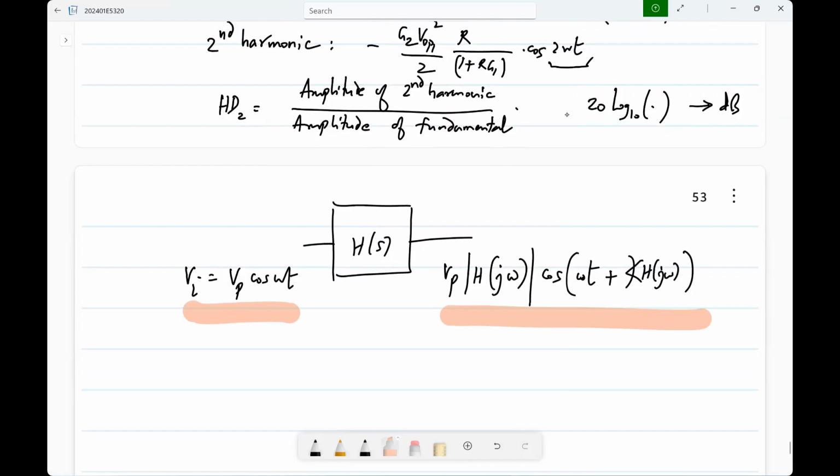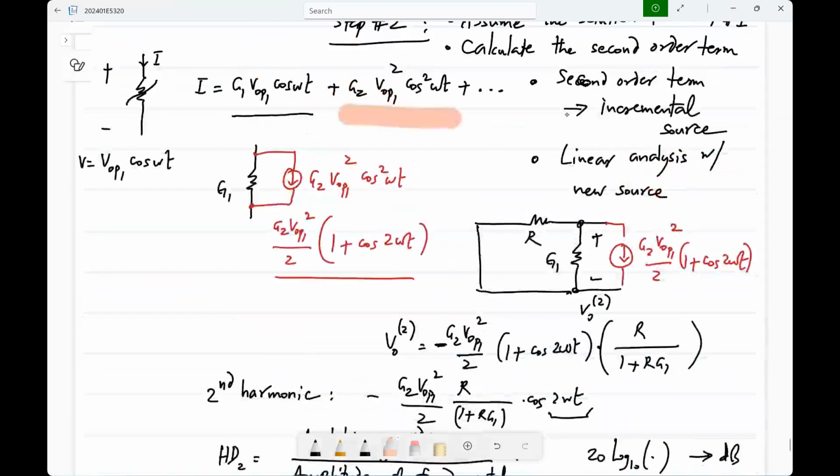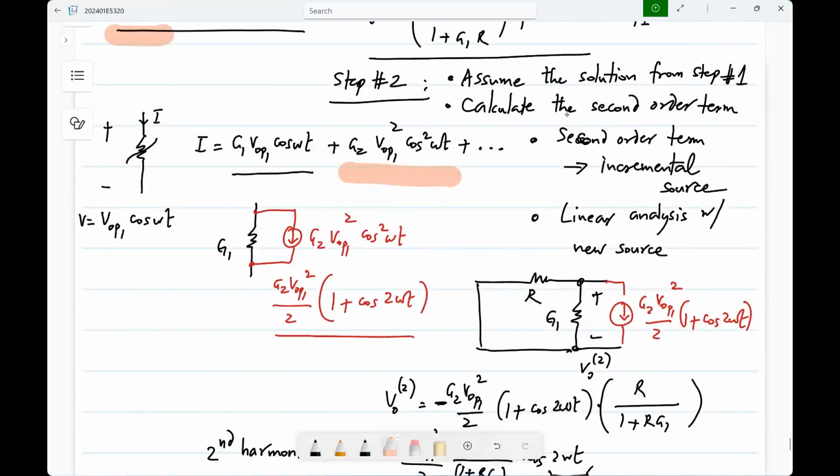Now in this distortion analysis, of course, you have to do it properly. In the first step, you can use Laplace transforms if you have capacitors, inductors, and so on. S will be j omega. In the second step, the excitation is at 2 omega. So then you substitute S with j times 2 omega. Okay. So you have to do that properly, keep track of it so that you get the time domain expressions, because this nonlinearity can be calculated from the time domain expressions, right? Okay. So in the second step, you can do Laplace domain analysis, but then you substitute S equals j 2 omega and so on. Is that fine?